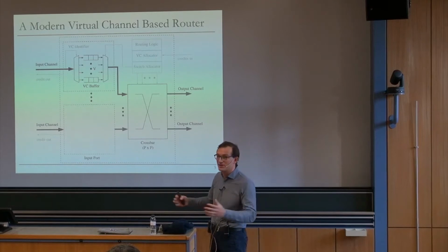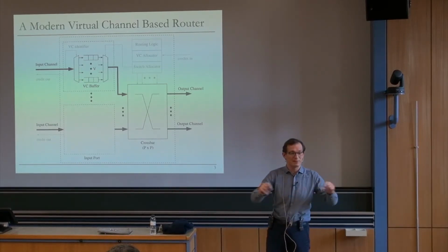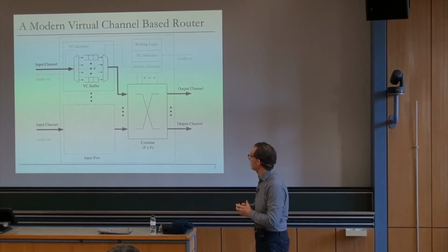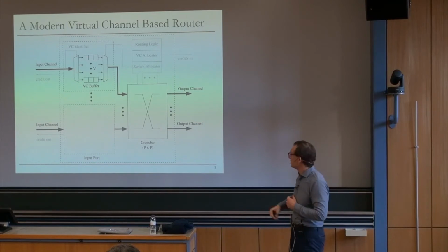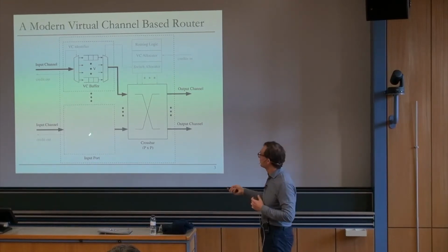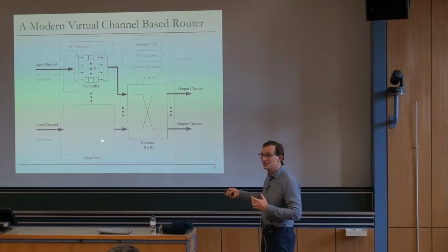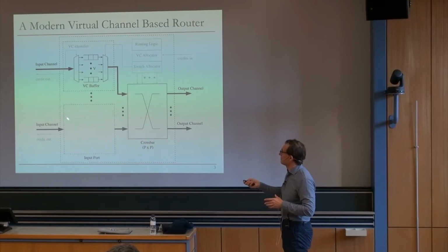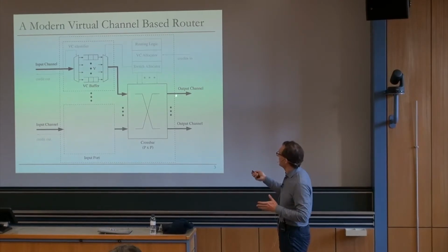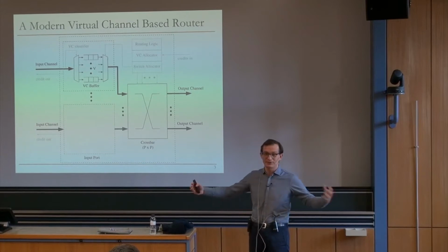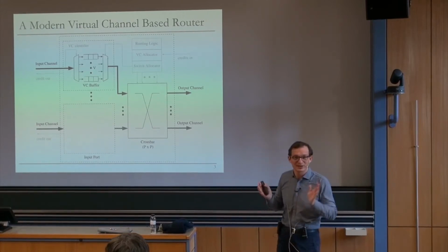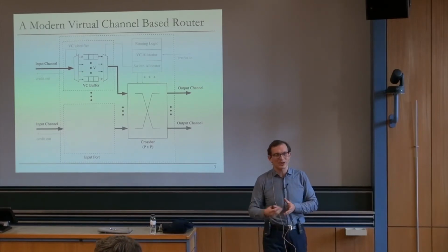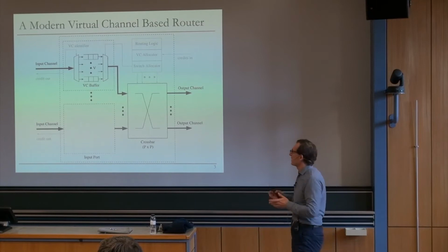But if you look at an out-of-order processor, it looks at a window of instructions. It can basically pick the instruction from any point in the queue. So it's really this window. It's not a FIFO queue. It's really an out-of-order scheduling window. You could do the same thing over here, actually. You could basically have a single huge buffer over here, and basically pick the oldest packet that wants to take an output port by searching the entire buffer, right? That's certainly possible. But people usually don't do it today because of the complexity associated with it. And historically, it hasn't moved that way, I guess.